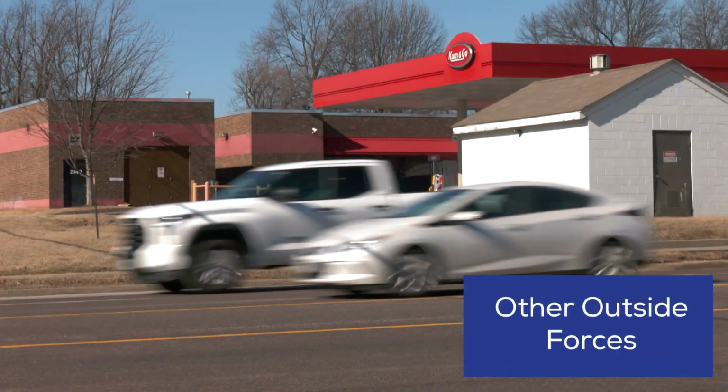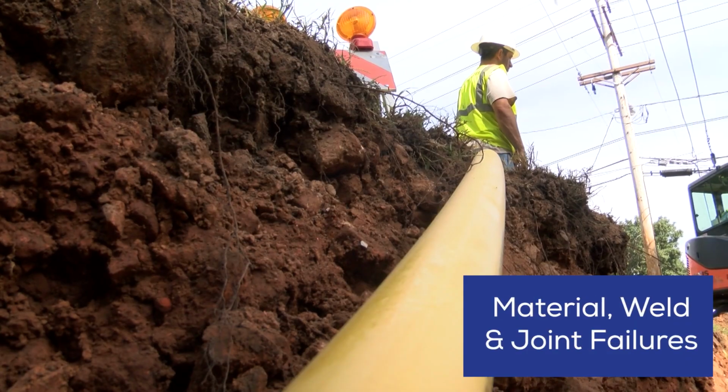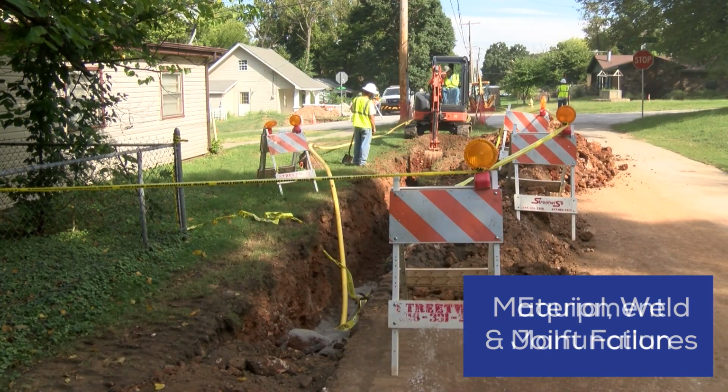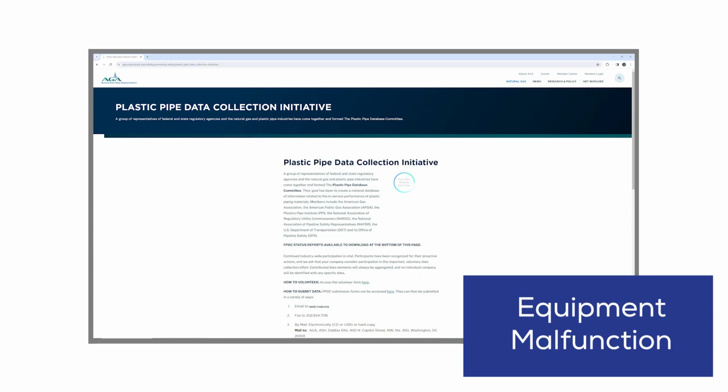Outside forces like vehicles pose potential threats. Install bollards around natural gas facilities in high-traffic areas. Replace leak-prone pipe materials, such as cast iron, and monitor vintage pipe connection points. Remove fittings and equipment with high probability of failure. Monitor industry trends, such as the AGA Plastic Pipe Database Committee, to stay informed on equipment and material updates.